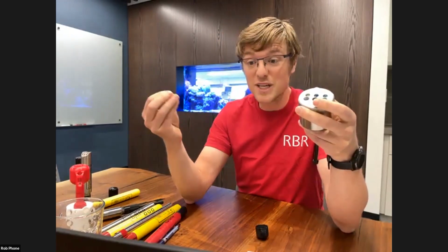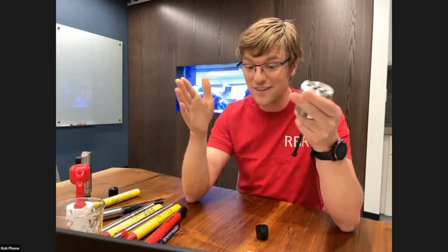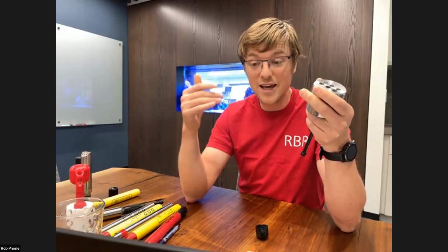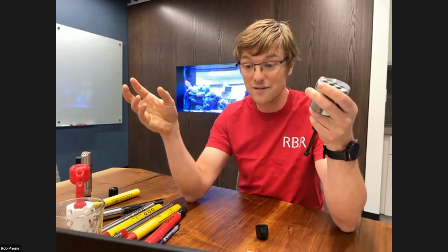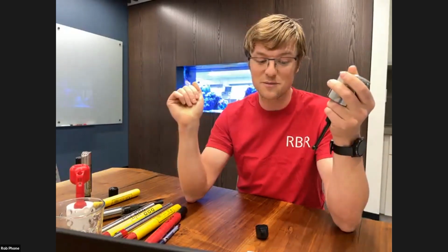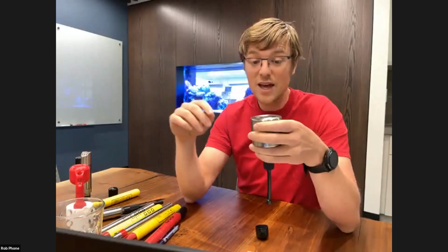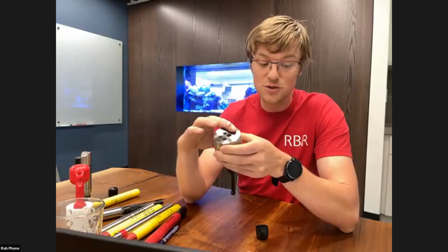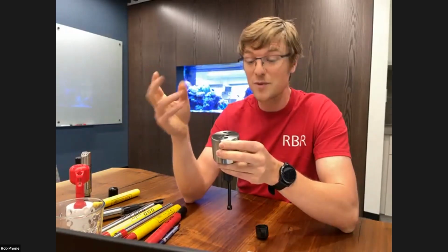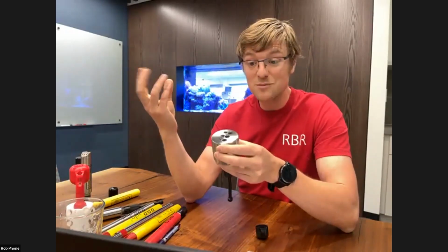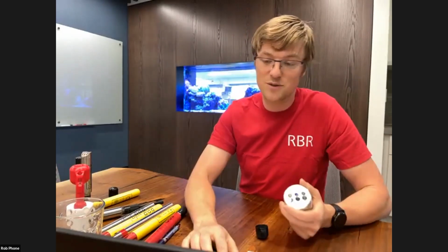Quite often LEDs have emission that's outside of the wavelength that's specified. Because we're detecting such weak fluorescence signals, we want to make sure that we don't have any of this out of band emission from the LEDs, because it'll end up polluting our signal. That's also why the window material choice is quite important. We selected materials that don't fluoresce, because if the material is being fluoresced by the light that we're emitting, it can then pollute our signal when it comes back to our detector.